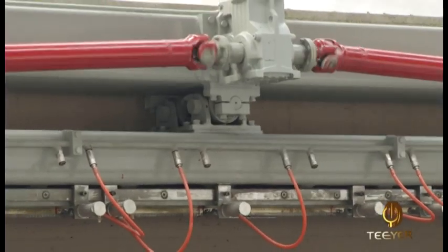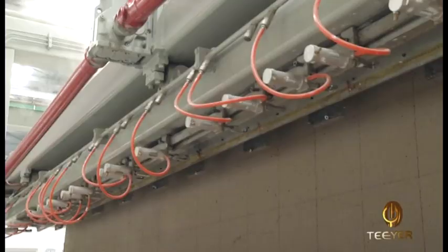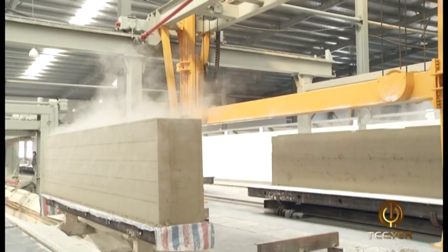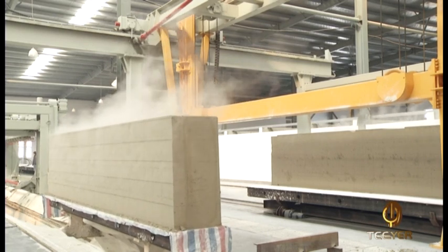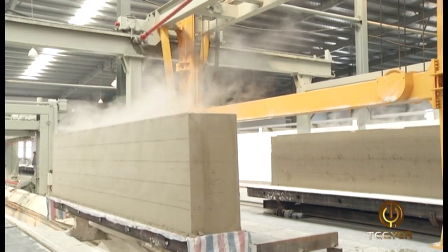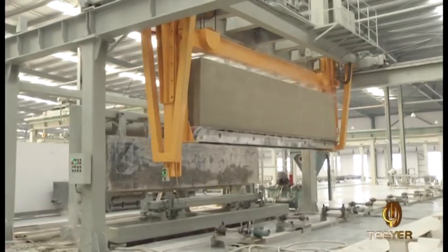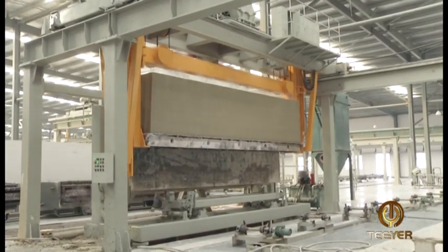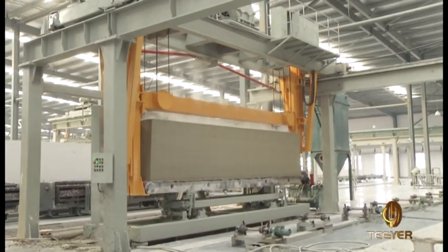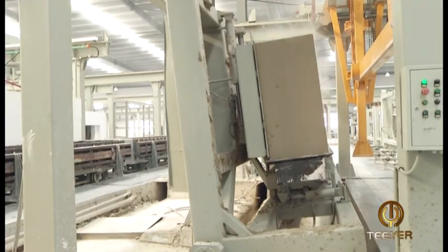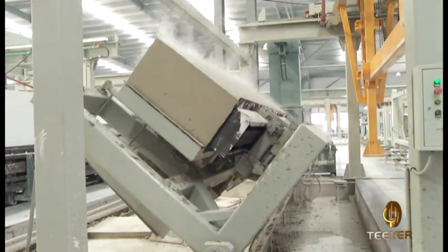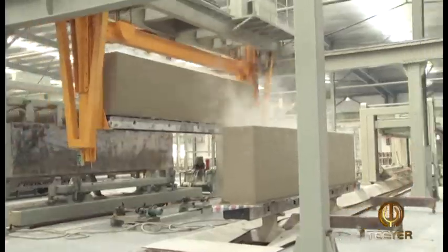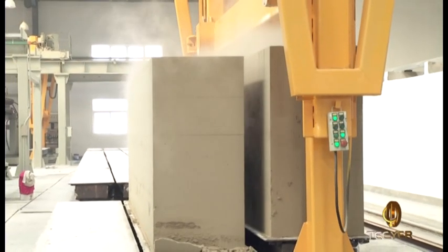During vertical cutting, the cylinder tension device will be swinging back and forth. After cutting, the second cutting cart comes to carry the block and the side plate to the semi-finished product hoister. The semi-finished product hoister takes the block to the tilting table, which removes up-down scrap materials on the body. And then the body is transported to the trolley for grouping.